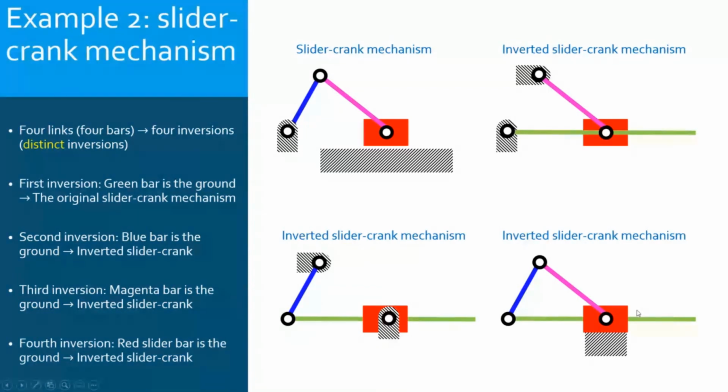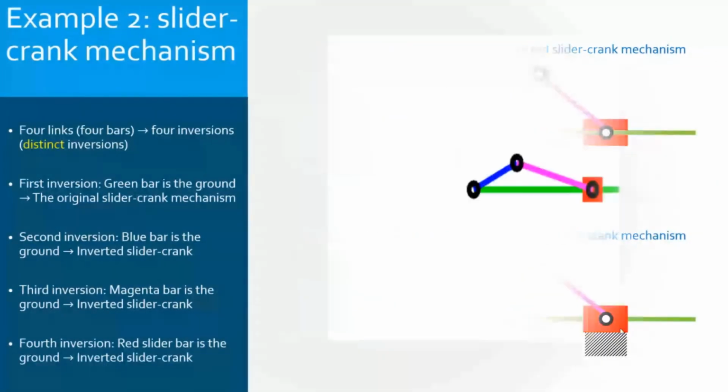Now here in this last fourth inversion, we didn't change it. We have completely schematized the ground here because it's necessary. If I remove the ground link here, we will not understand the type of motion. So we will keep it. We will keep representing the ground link here, the slider, only if it is necessary in the analysis or to understand the motion or the type of motion of the mechanism. So these are how we schematize the 4 inversions,